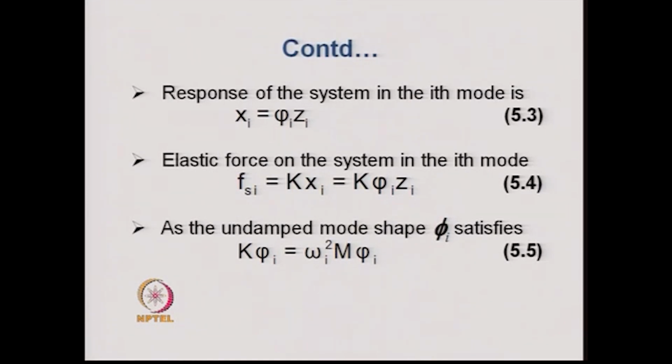So, in this fashion one can find out the responses in any mode of vibration, and once we obtain the vibrations in different modes of vibration, then we sum up the time histories of these responses to obtain the final response of the structure, and the summation is carried out for m number of modes that we consider for the analysis.